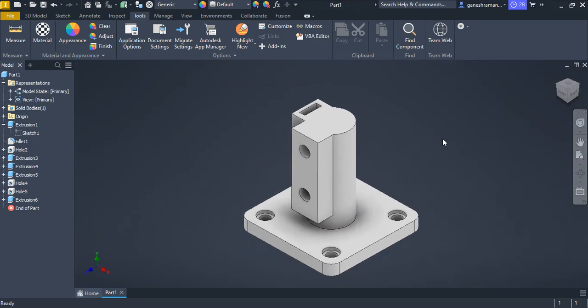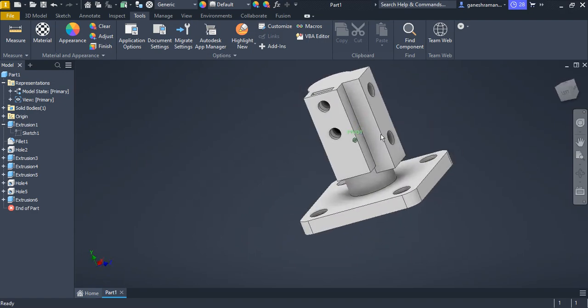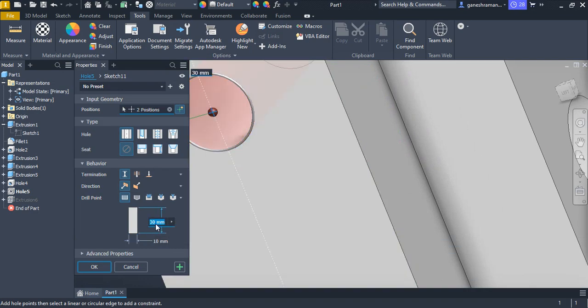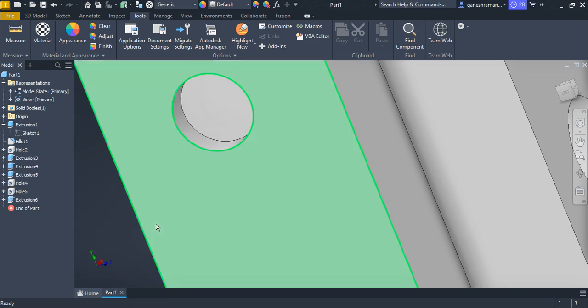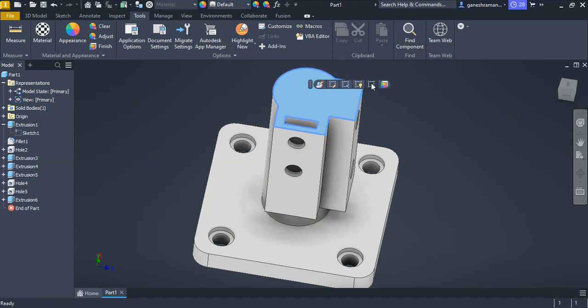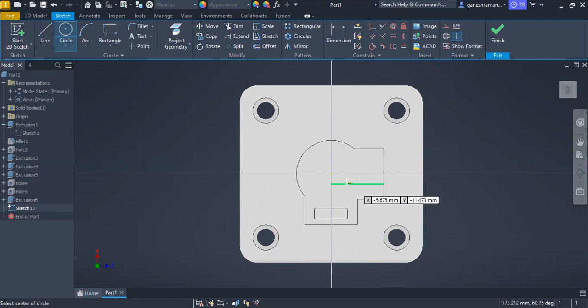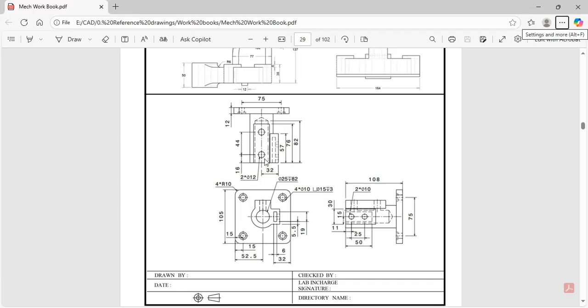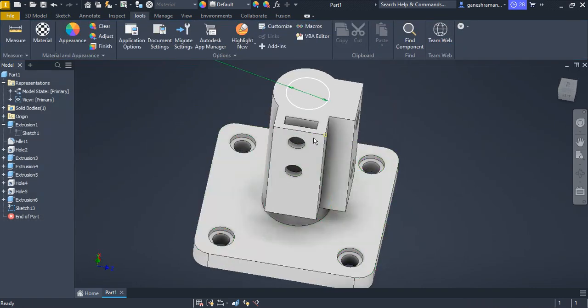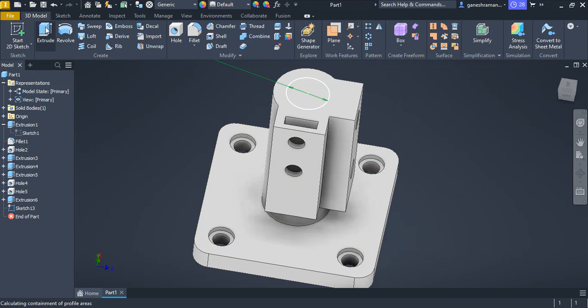That's fine. So select this whole feature and edit and choose the depth as 3.5 only, or 4. That's it. Okay, set the surface, add sketch and choose one circle. What is the diameter of this circle? 25 is the diameter. Depth is up to 82. So 25, enter. Click on the S key from your keyboard. You will get out of sketch workbench. So that's fine.